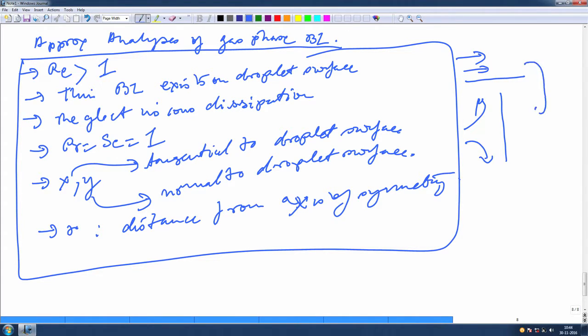So, combining these two, and also if you know the Falkner-Skan type of solutions, that means if you have a surface inclined at any particular angle, there is a class of solutions available which are called Falkner-Skan. Okay. So, that looks like a Blasius solution, but it is applicable for any level of inclination. Blasius solution is only available for a flat plate, right, with zero pressure gradient. In the case of Hiemenz flow it is different, and Falkner-Skan basically includes these two as special cases.